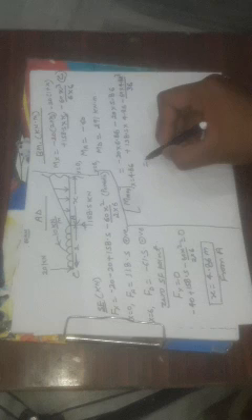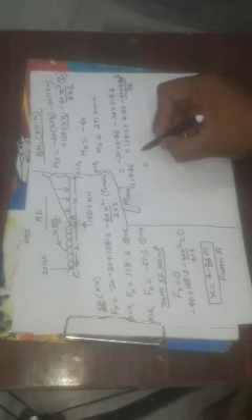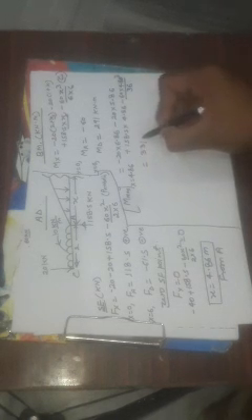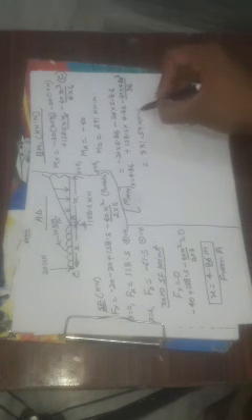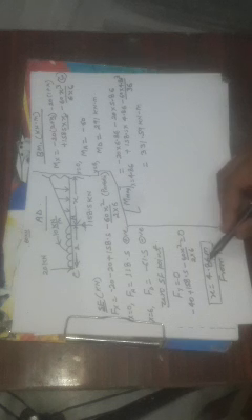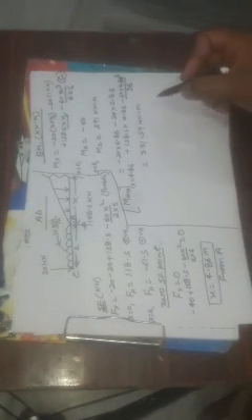When we calculate, we will find the maximum bending moment value is 331.59 kilonewton meter, right? So at this zero shear force point, the bending moment value is maximum.